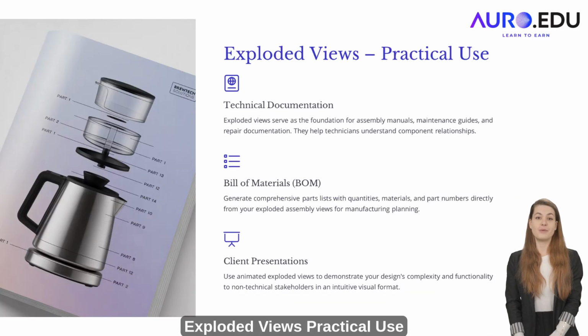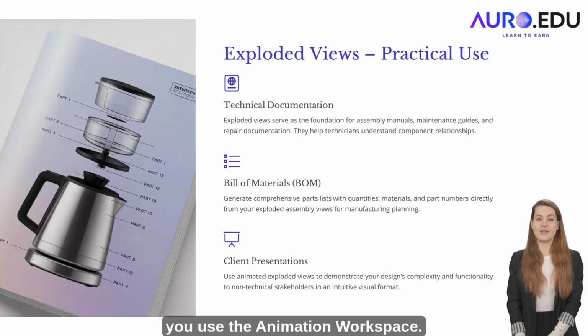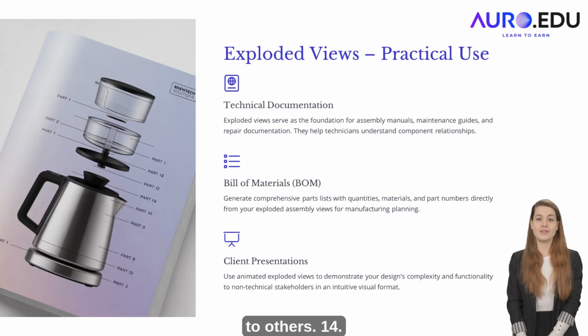13. Exploded views. Practical use. Exploded views are often used in manuals, documentation, and manufacturing. You can also generate a bill of materials, BOM, from them. In Fusion 360, you use the animation workspace. In SolidWorks, the Exploded View tool does the job. These visuals are great for communicating design intent to others.